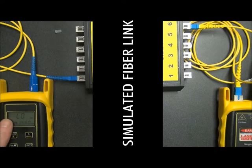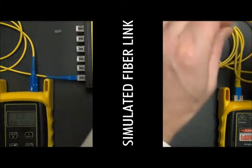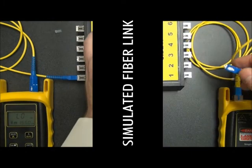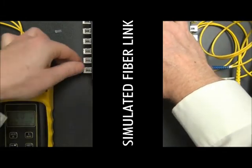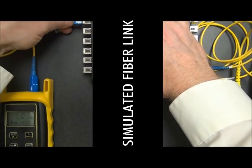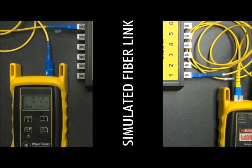Okay, again, remember that low means no light is coming in because we are not using the 1550 reference cable. Once we connect, we will get a reading. So we'll take the 1550 reference cable and plug it back into port number 1, and then plug the power meter cable into port number 1 as well. As you can see, we get a power reading.